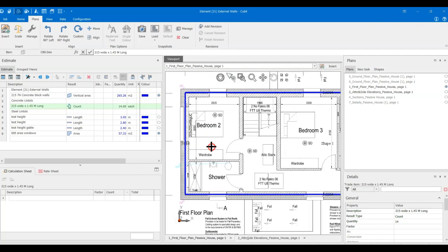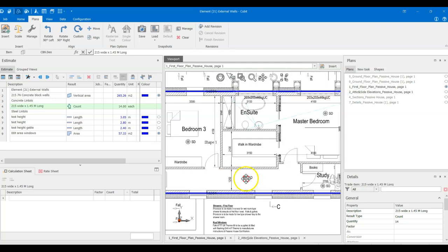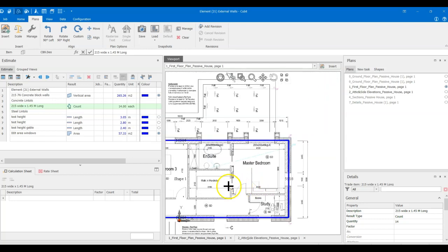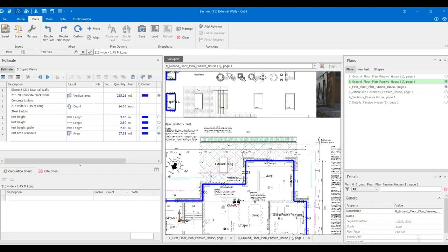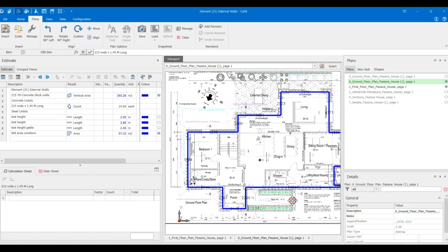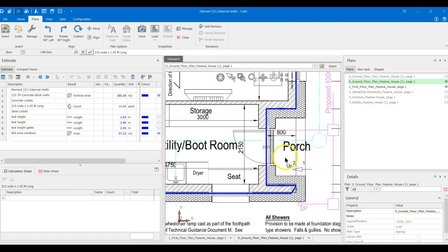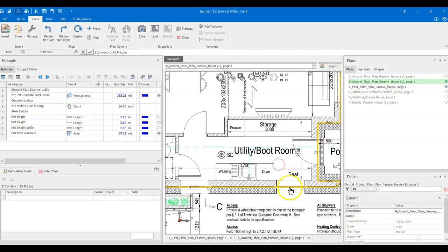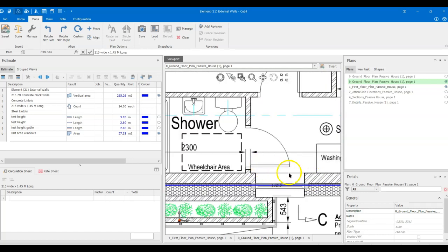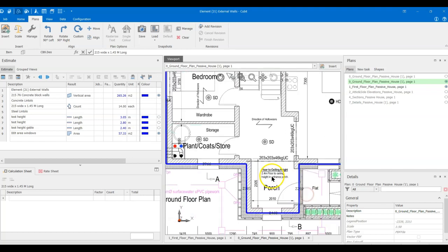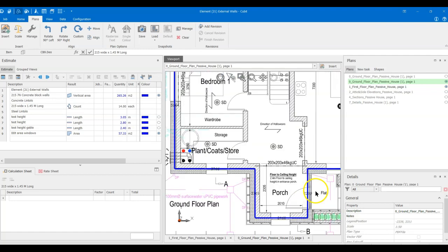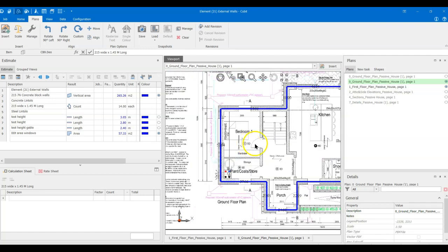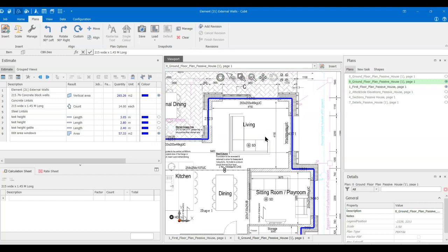I'm just checking through this plan. I've measured all those small windows already, so there's nothing more on the first floor plan. The question is, what's the ground floor plan like? Generally speaking, different engineers differ, but once you go over, say, 1600 or 1800, they tend to go for steel. Front porch, there's no reference to steel there. Window seat, no reference to steel there. I'm just manually checking through. I can see I have a steel there. I've no reference to a steel there, so I should have a concrete head that's longer than standard there. It's about 1600. I've steel in there, and I've steel elsewhere.